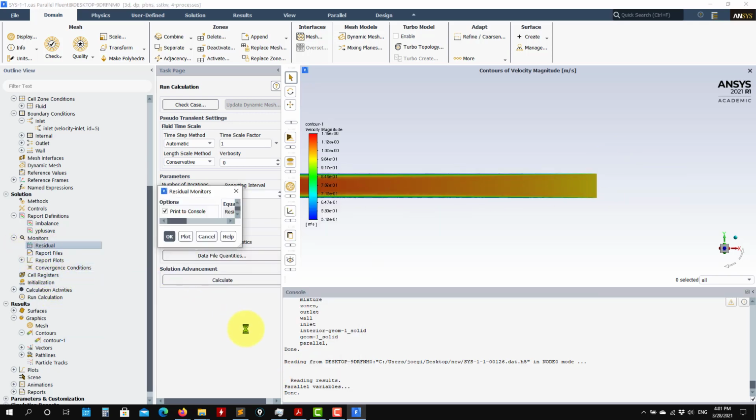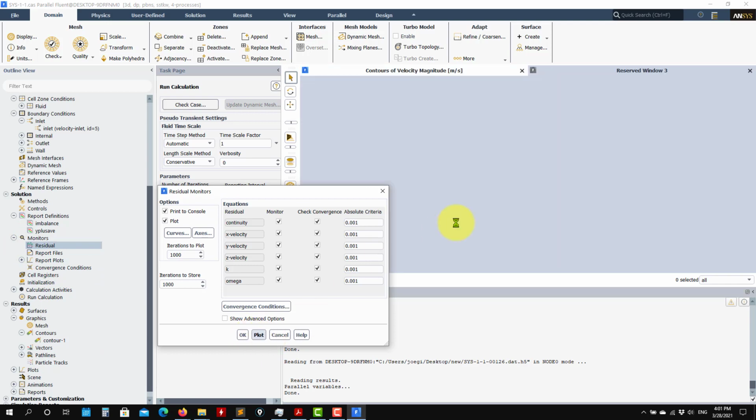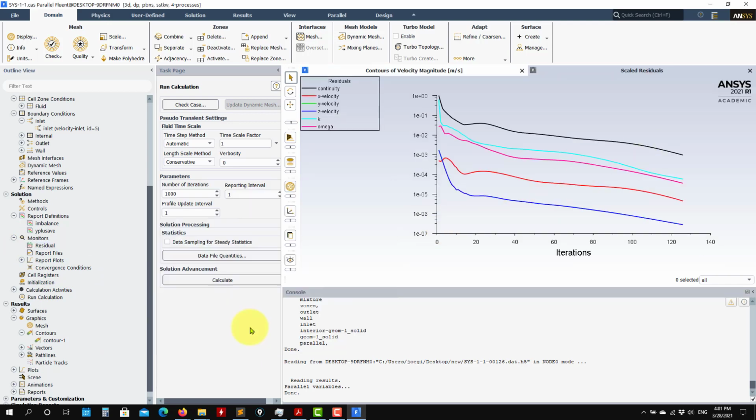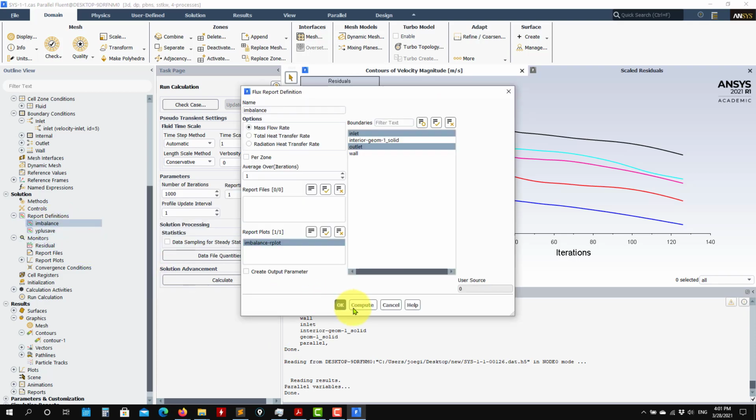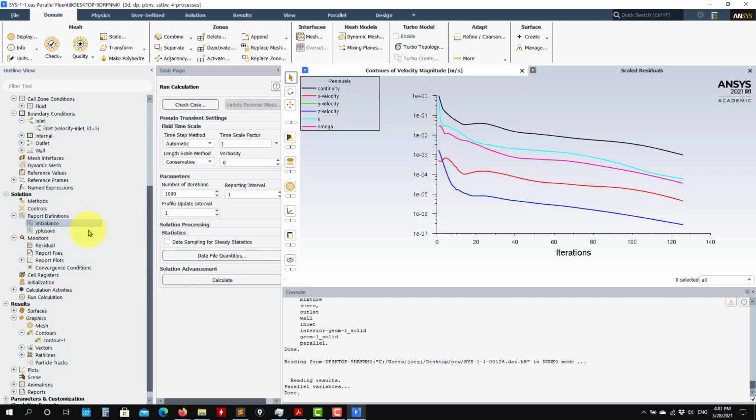And you can go here and you will see that you have the monitors. We can plot the monitors. We cannot plot this one because we didn't save the text file, but if you save the text file, you will be able to plot those two. But we saw that the y plus value was still oscillating a little bit. So let's keep running this simulation.